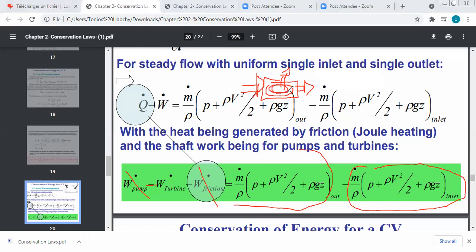So your only source of energy in a steady application will be the flux that is crossing your control surface. Since I have work that is delivered to the environment and I have a steady application, this energy will come from the crossing flux that is coming in. So I will take a part of its energy. This is why the energy of the flux out will be lower than the energy of the flux in if I just have a turbine.